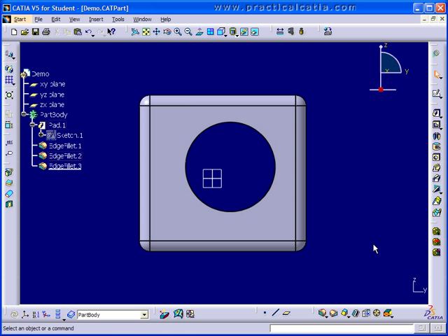And I assume that it's backwards because the software is written by the French, and I believe that instead of a third angle projection, they're using first angle projection. So I believe that's why the disparity between how we would normally be looking at the axes for a front view versus how they look at it. And there is a way to change that now. We'll get into that in a few minutes. Then we have back view, left view, right view, top view, bottom view, and then we have named views.